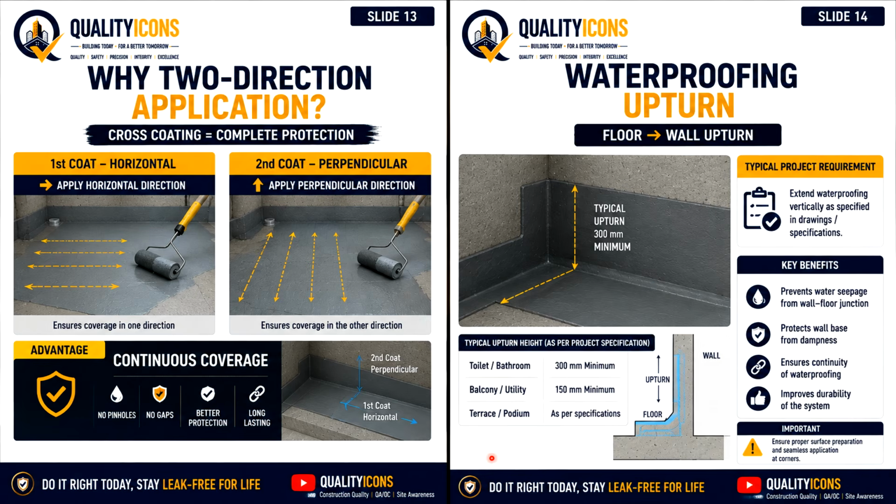Next is the waterproofing upturn. Typical upturn is 300 mm minimum. This is the upturn. In the presentation, a typical toilet or bathroom upturn is shown as approximately 300 mm minimum. But the actual project requirement should always govern. Particular attention is required at corners and wall-floor junctions to maintain continuous waterproofing.